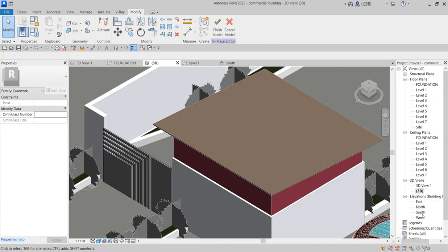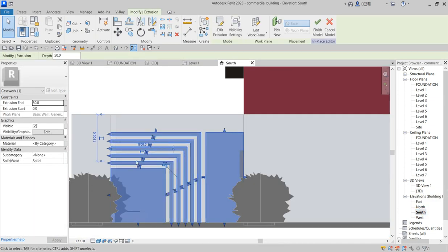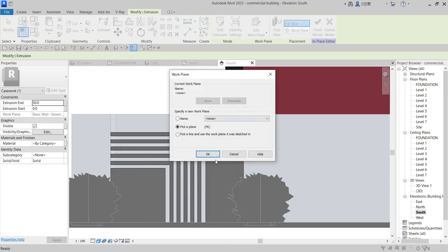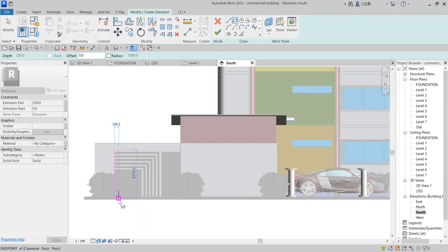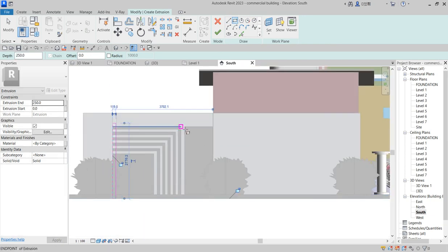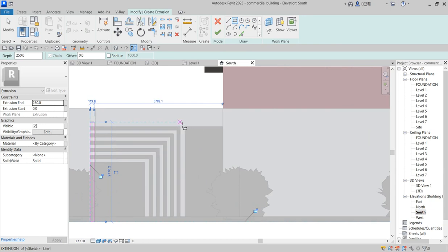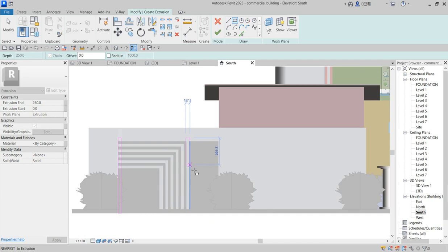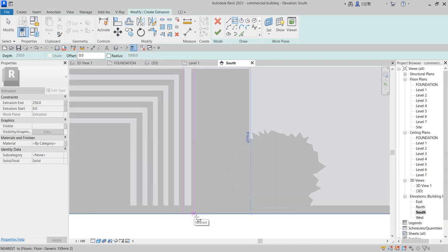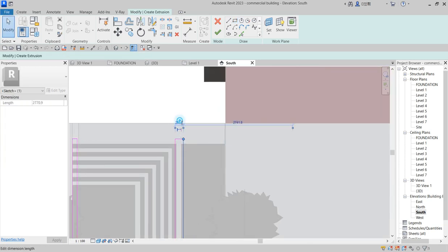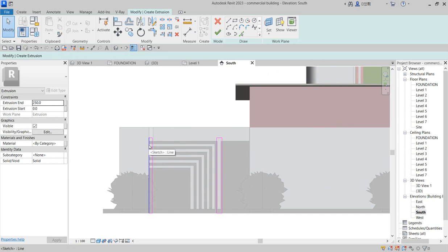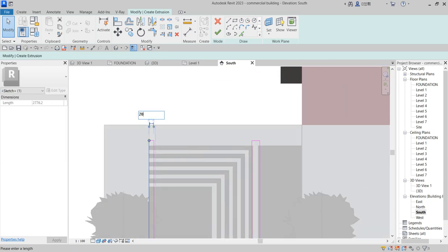We go back to the south elevation, edit that and say go similar. You are using the reference of that gate to do whatsoever you want. At this point, you draw a pole, that is the holding pole for the gate. There's something inside here too for the gate. Tap here and make it 200. It's going to be a flat golden pole. Do the same thing, 200.